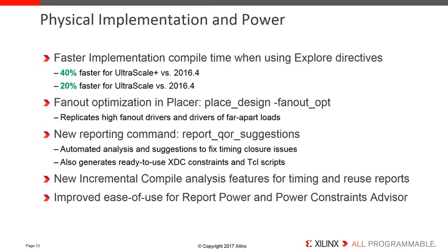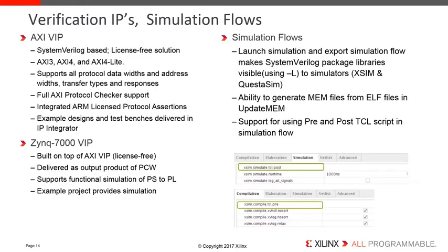The new Report QOR Suggestions command checks the design for certain problems that are preventing design closure and makes suggestions on how to fix them, and also generates ready-to-use XDC constraints and Tcl scripts. New incremental compile analysis features for timing and cell reuse reports, and improve ease of use for Report Power and Power Constraints Advisor.